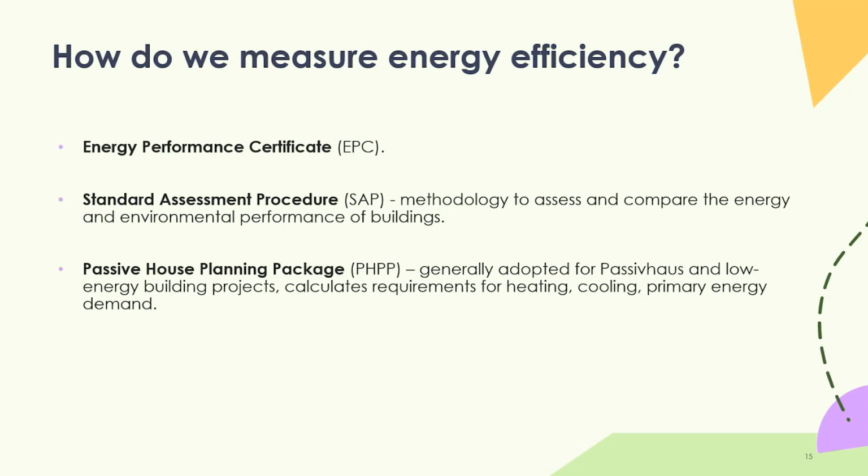There's also other methodologies out there for measuring energy efficiency. So if you're doing the really high level type of retrofit, you might use PHPP, which is Passive House Planning Package. And that's generally adopted for passive house, or in retrofit, the retrofit equivalent standard for passive house, which is for new builds, is EnerPHit. So if you're doing something like that, which is normally a very low energy building, lots of very clever stuff, it faces the right way to get the maximum amount of solar gain and releases the heat over the course of the day carefully, and it's all very precise and a very airtight building.